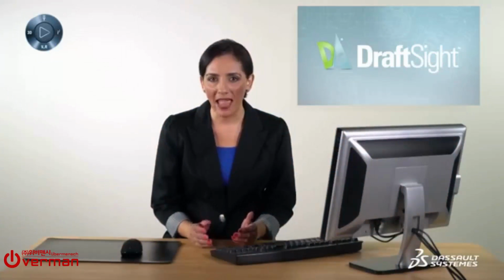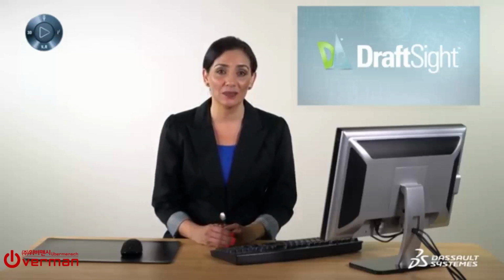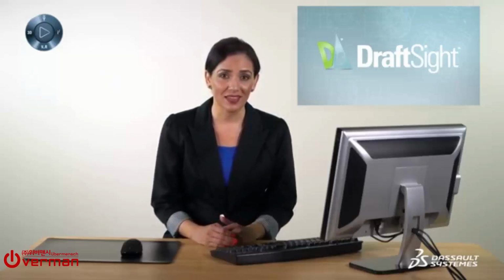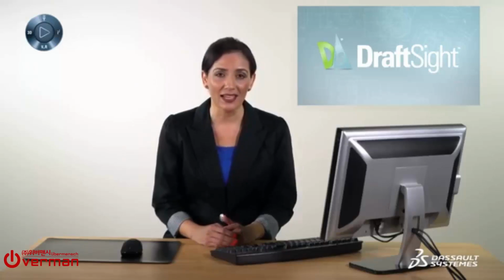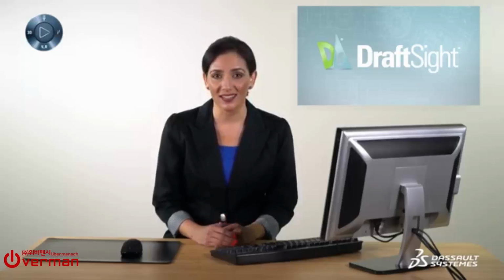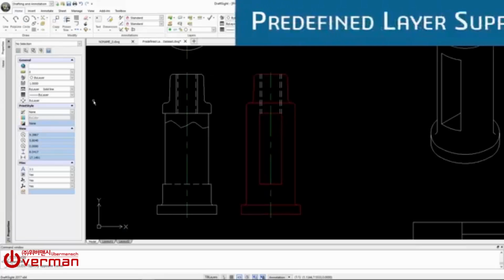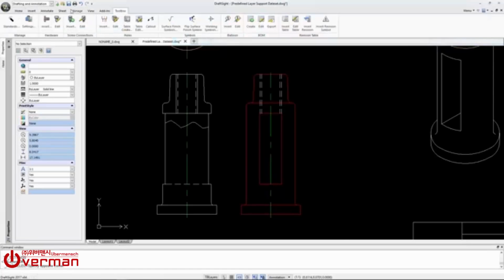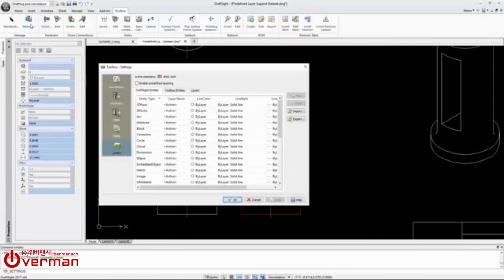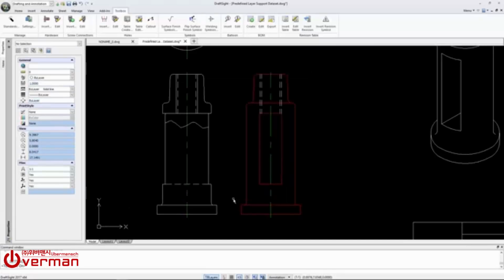How often have you had to manually switch layers between different entity types because they were placed on the wrong layer? What about wasting time to manually calculate a midpoint in order to insert a center line in between two parallel lines or arcs? The Draftsight 2017 Predefined Layer Support tool automates the layer assignment process by mapping predefined layers to common entity types and toolbox features. You no longer need to worry that your dimensions, hatching, or other entities are on the correct layer. Once the settings are configured, Draftsight automatically maintains these for you.